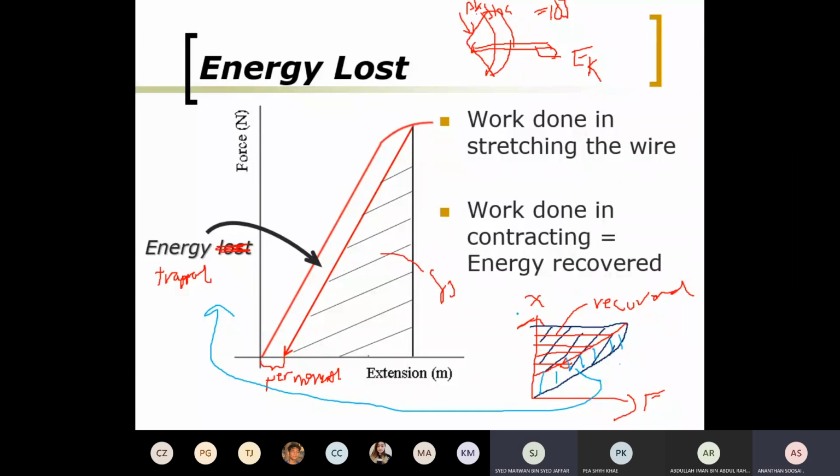Okay, so if you conduct an experiment, you get the data already. You load it, the line will go up. When you unload it, the line will go down. So you can see finally where the permanent deformation is when you conduct the experiment. If in the exam you didn't conduct an experiment, they only ask you to sketch, then you can draw a small permanent deformation to show that there will be a permanent deformation. How much, you can't identify because you didn't conduct the experiment. Understand? Okay, so let's proceed.